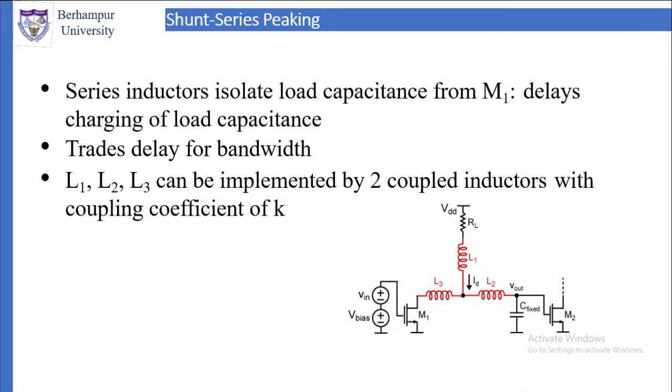Once you determine which load line you are going to use, at the center of the load line you fix the Q point. Of course, if you go to power amplifier, then it will be different: Class B amplifier, Class A amplifier, or Class C amplifier. There you will fix it at one of the ends of the load line, and we will use two amplifiers, one to push, other to pull.